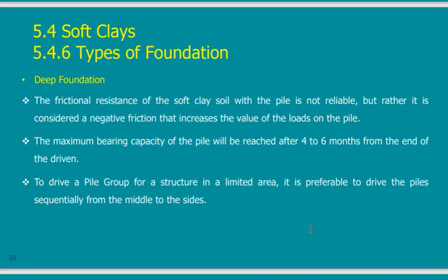Why? Because soft soil is neighboring the pile, and it is touching the pile. But soft soil, with time, will settle because of consolidation.